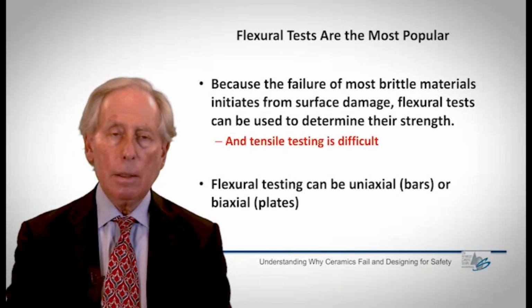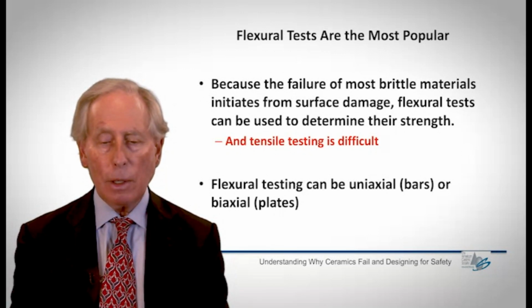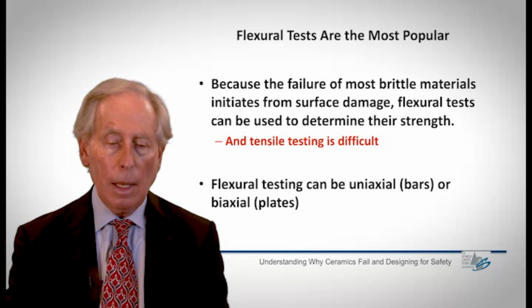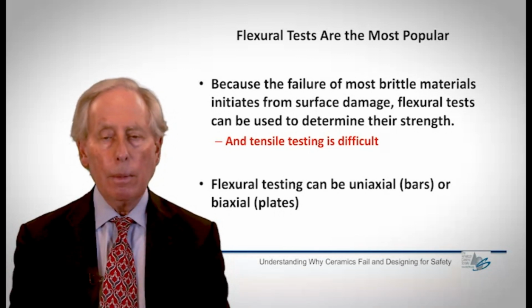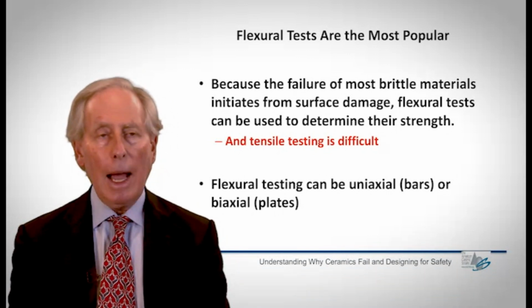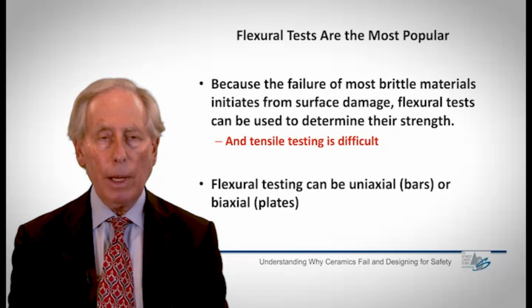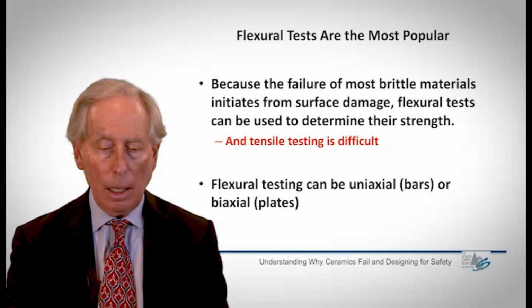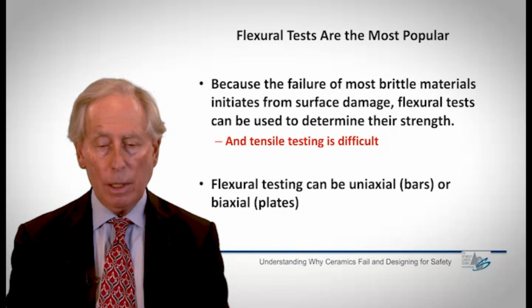And in doing this, flexural tests are by far the most popular. They're the easiest to conduct. Because we are failing from surface flaws in the material, I can run a flexural test, and it's going to fail from the same flaws that would cause failure in the component because they're going to be machined in the same way. And tensile testing, as I'll point out in just a few minutes, is difficult.